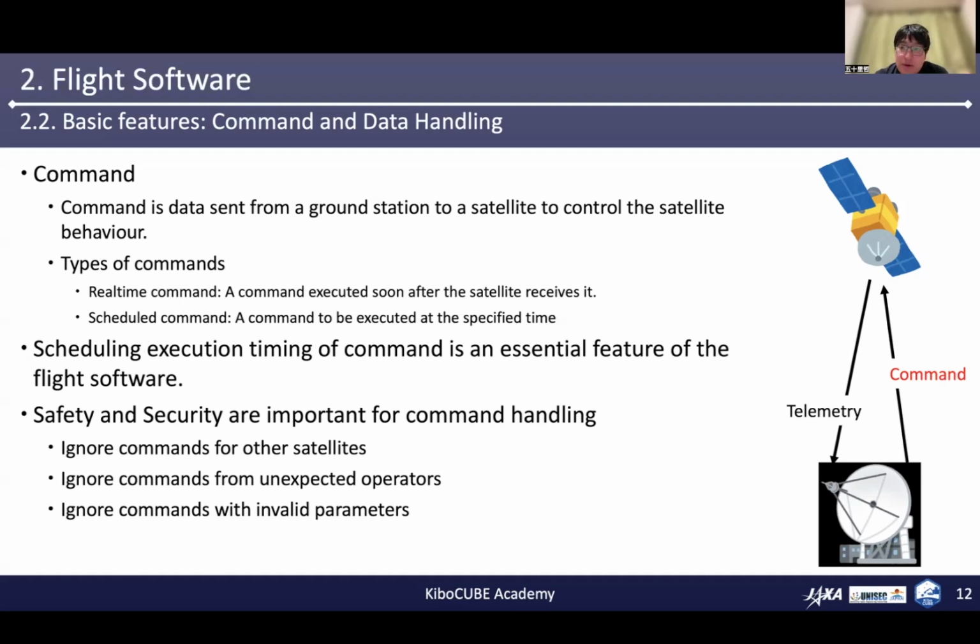So to handle the scheduled command, scheduling the execution timing of command is an essential feature of the flight software. And when we consider the command, we also need to care about the safety and security of the command. Of course, we need to ignore the commands for other satellites or commands from unexpected operators. And of course, satellites should ignore the commands with invalid parameters to protect the satellite.